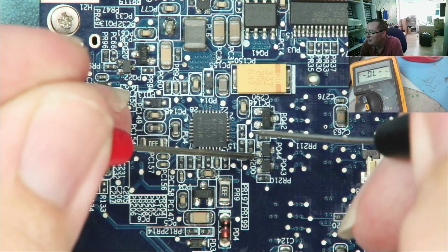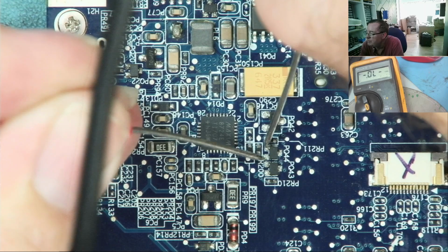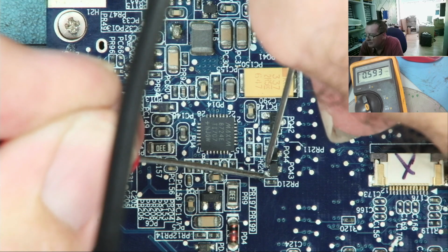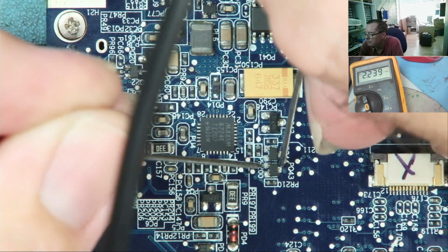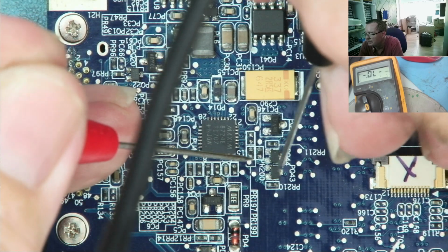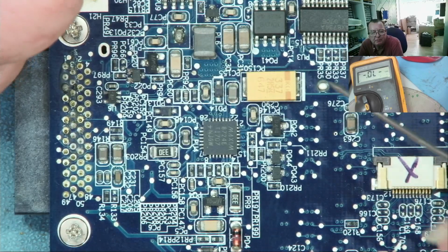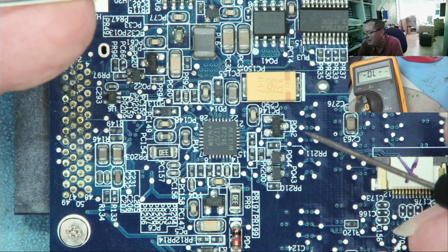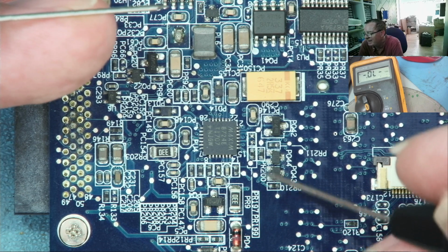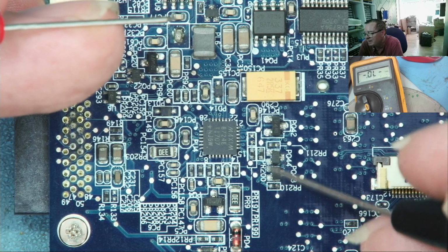On this one, from here to here, is open. And this one, I see a diode junction, okay? Now, we can also go from here to here. There's nothing. So there's no short between those two pins on this one. I can think of no failure mode that would cause that component to fail in that way. It just seems to be the same as this one, the only difference being that this has a diode somewhere here, quite possibly inside this chip, which is effectively between there and there.